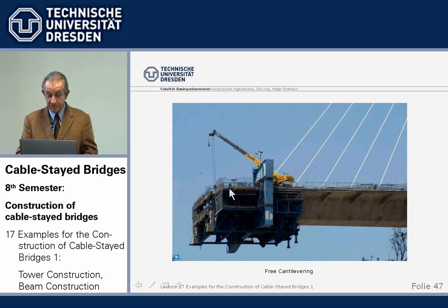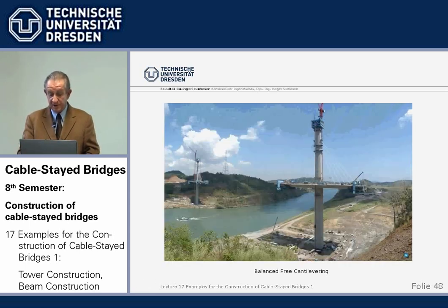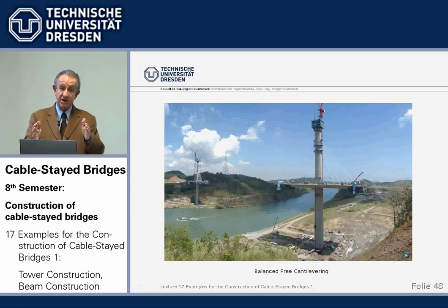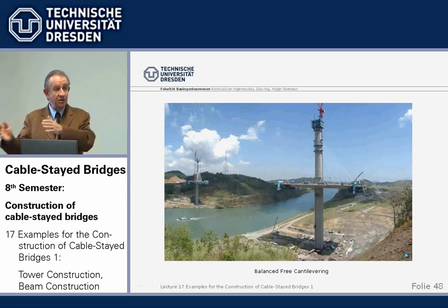And this is the short form, again 4.5 meters deep for 6 meters. There the beam can carry that itself, so we don't need any auxiliary. We see here free cantilevering parallel to both sides. Again, because of the short lengths of elements, we had little weight left or right out of balance. So the moment about the tower was fairly small, and we didn't need any auxiliary staying of the tower.